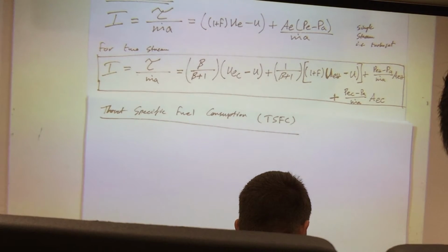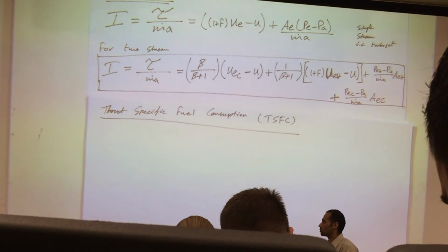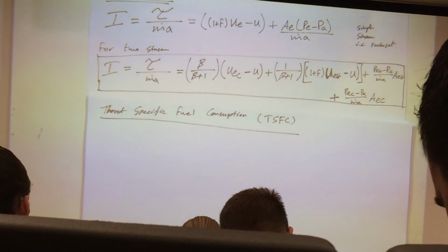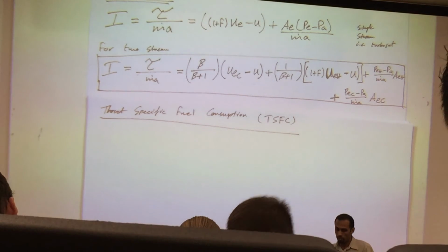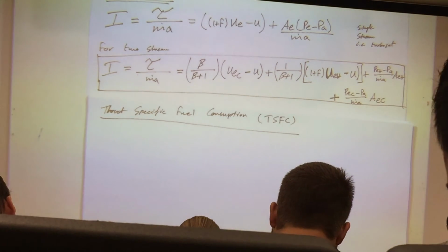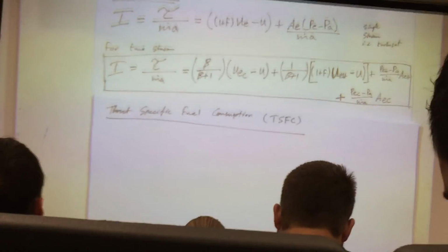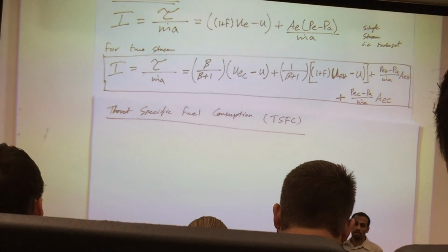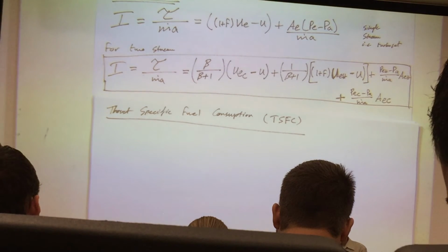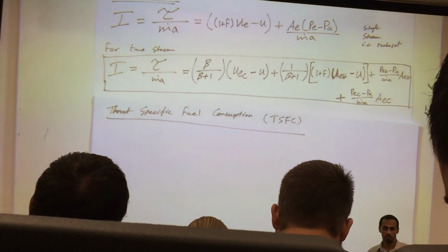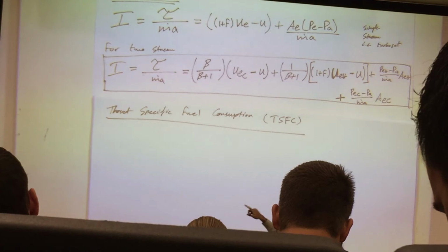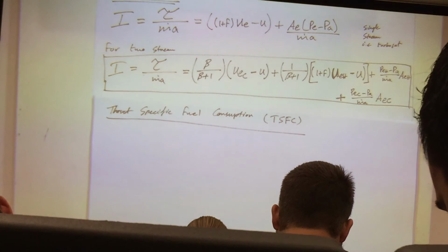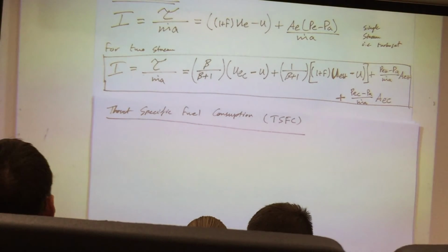Whether you're doing military engines or commercial engines, you're most likely to have a customer, whether it's an Air Force or Boeing or Lockheed, and they come to say, I have an aircraft that weighs this much and I need to move it at this much thrust. So here's the thrust value, and I want to maintain a TSFC of this value. So you go and design the engine based on these parameters, and tailor your area ratios, your pressures, your fuel air ratios, your bypass ratios, and all that based on these parameters that you get as an output.